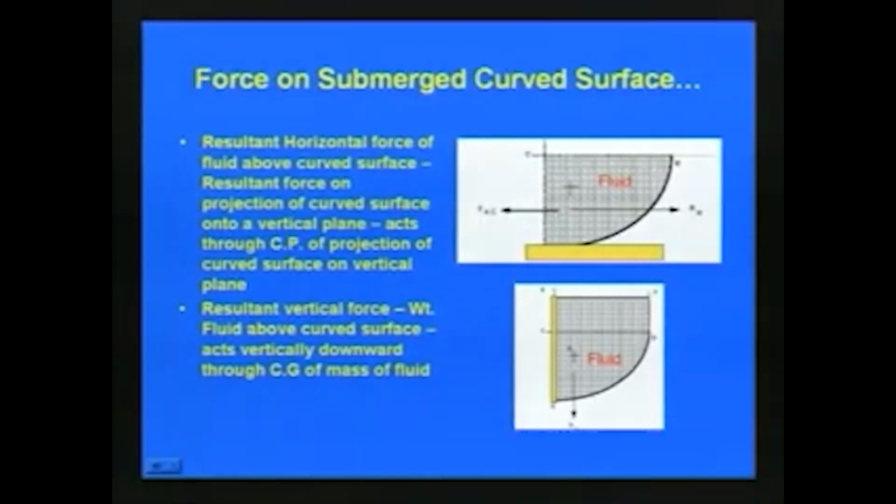Similarly, in the case of the vertical component, as far as this gate is concerned, the resultant vertical force will be the weight of fluid above the curved surface. So, here we have the curved surface. What will be the weight of fluid above this curved surface, that we can determine, and then that acts through the center of gravity of the mass of fluid, the mass of fluid just above the curved surface.